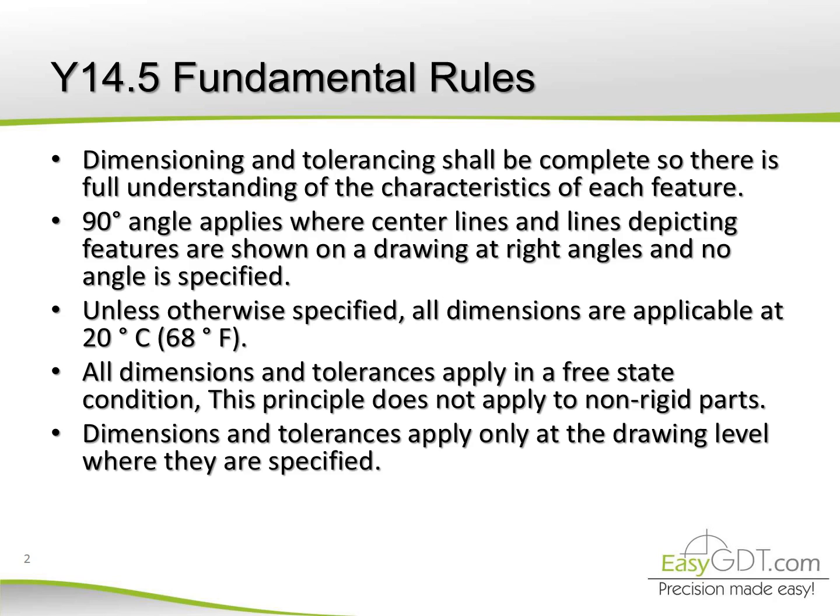Dimensions and tolerances apply only at the drawing level where they are specified. You can specify dimensions for a part in different drawings. All the information should be present in the current drawing. Let's continue looking at more rules.